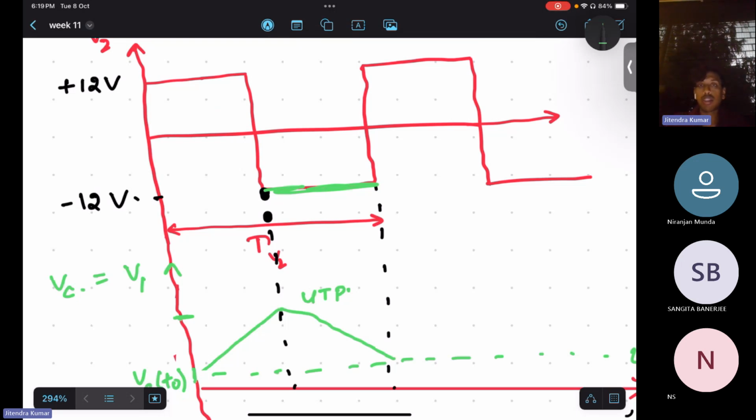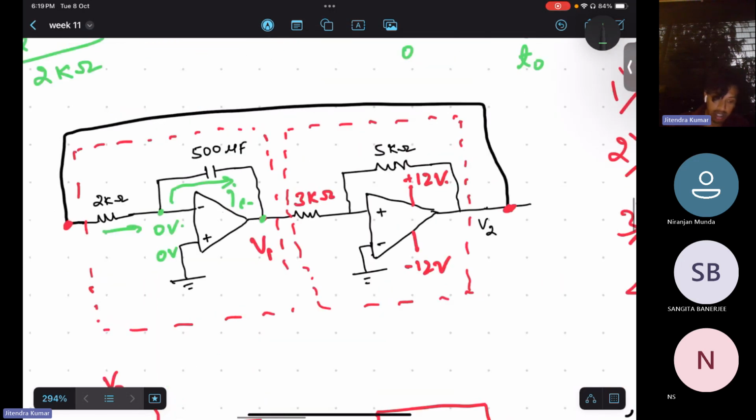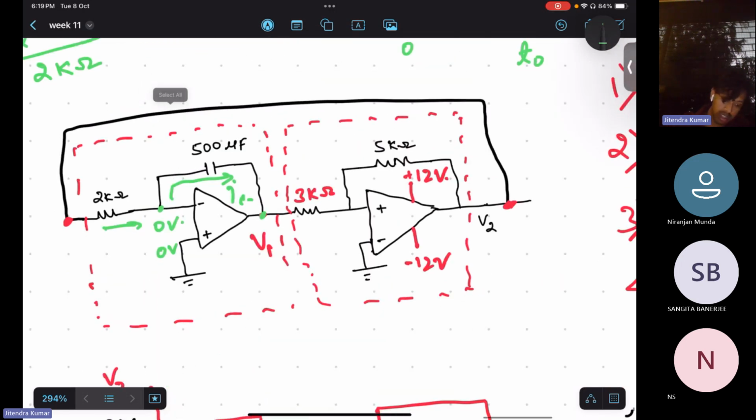So that approach, I don't think should work here, because if you see the time constant, tau is equal to RC. So R is 0 in this circuit, right? Here, no R is connected. So in that way, our time constant will be how much? 0. Means it is zero. Yes, yes. So we have to look for any other approach.